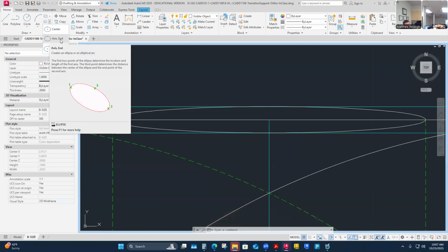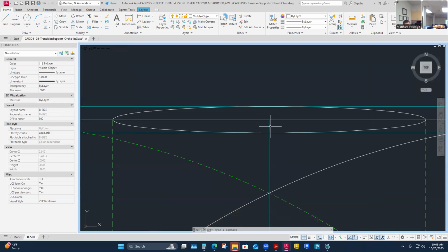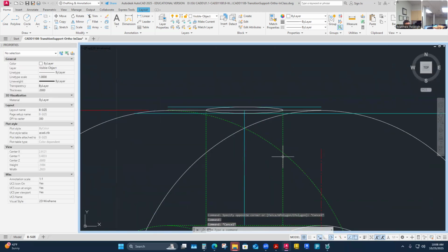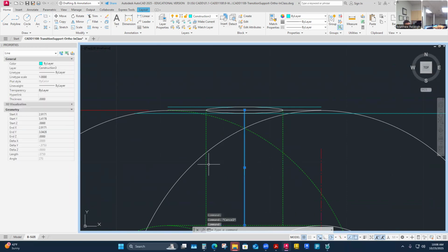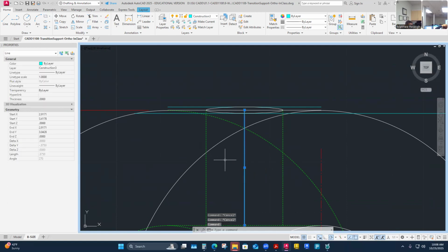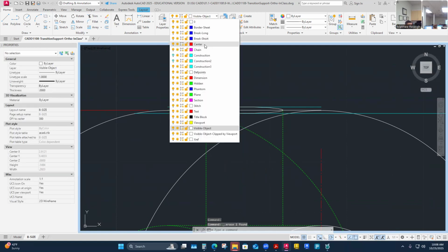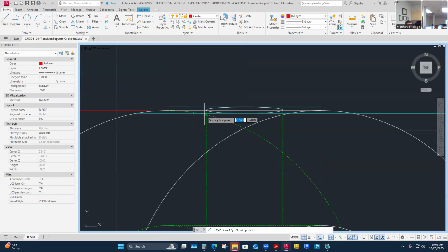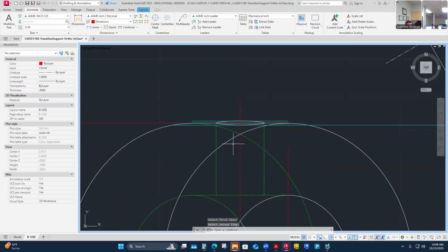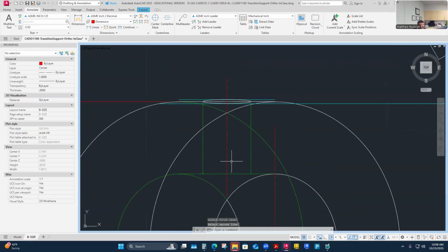Like center. This one? Just add a center line of that slot. I did, yeah. Technically, I did an offset of this, but I actually do want that to become a center line. One of the ways I could have done that, I'll delete it real quick. I could have come in here on my center line layer and picked my center line command. This does need a center line. It's one thing I hadn't finished there. That thing should have a center line down through it.